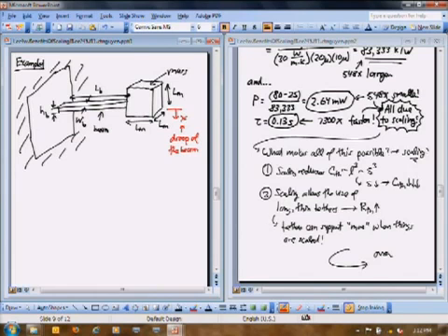And so in order to model that whole thing, I want to model the droop of that beam. Let me say a few things about this beam first. First of all, the droop is going to be governed by the stiffness of the beam. So let's just say that K is the stiffness. But this beam is going to have a different stiffness along its whole length. We'll learn more about that later on in the class. But let me just say, to be correct about this, that this is the stiffness at this point right here where it attaches to the block, the mass.